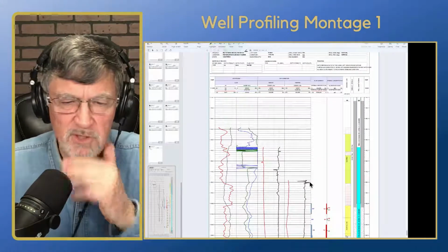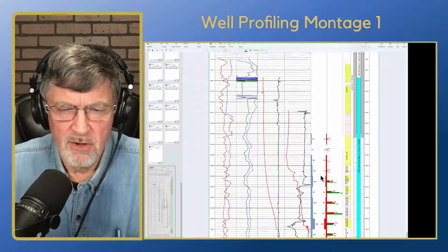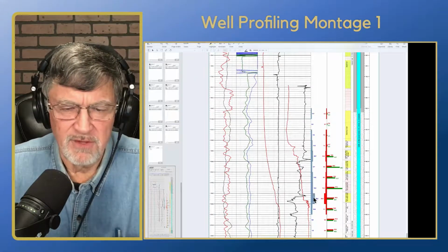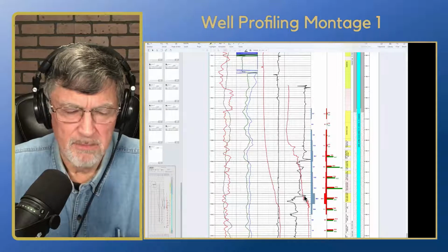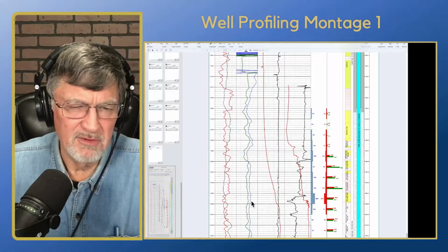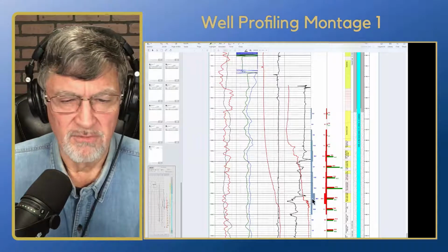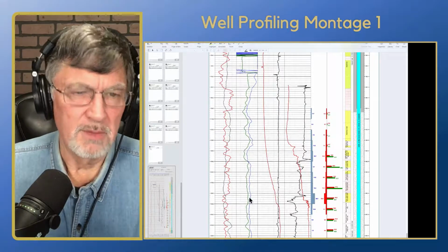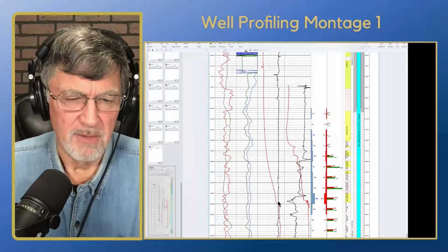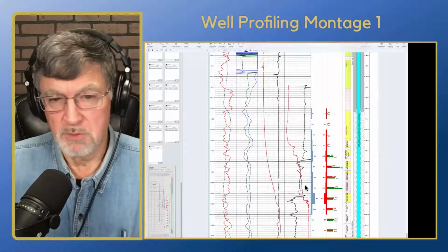We are then looking at the flow summary here in this column here. And you see the summary, our greatest flow is right in here, and then down around between 180 and 190 feet. So that's that peak there. Interestingly enough, not a real distinctive peak on the resistivity log, but that therein is our flow, and you can see on the ambient flow, which would be where the resistivity would be measured under non-pumping conditions. You can see it's fairly flat there, but under pumping conditions, this is the most productive zone in the well.